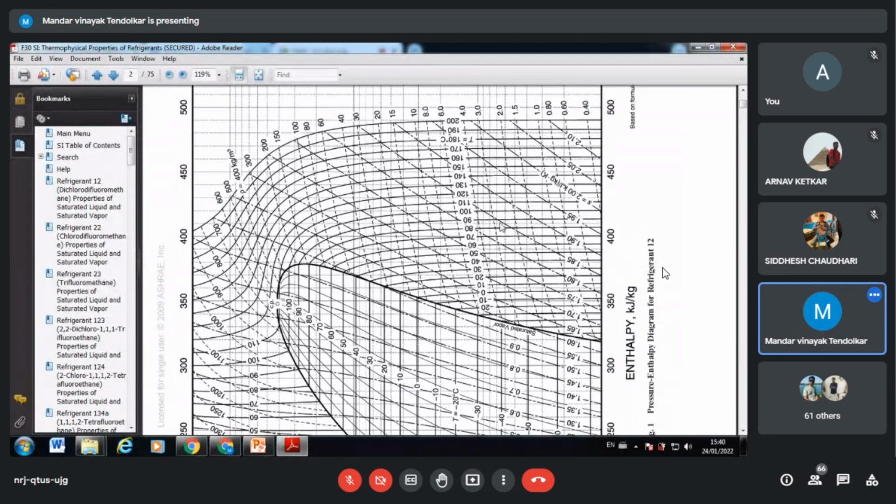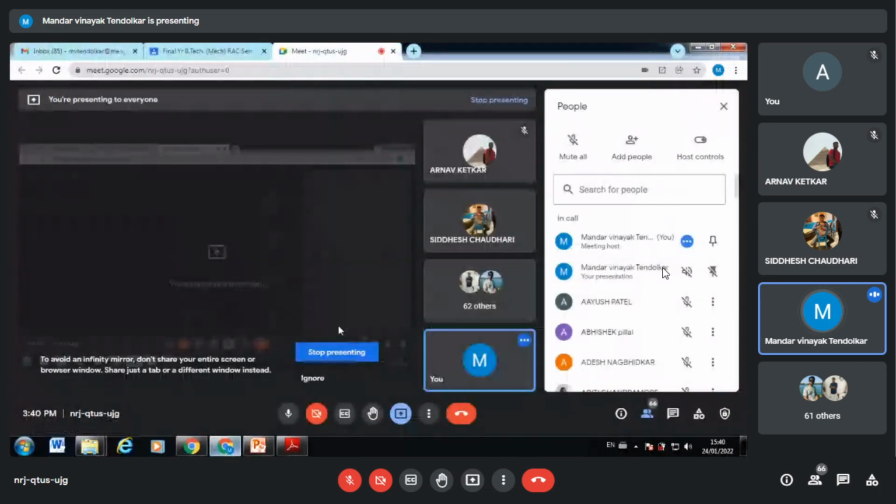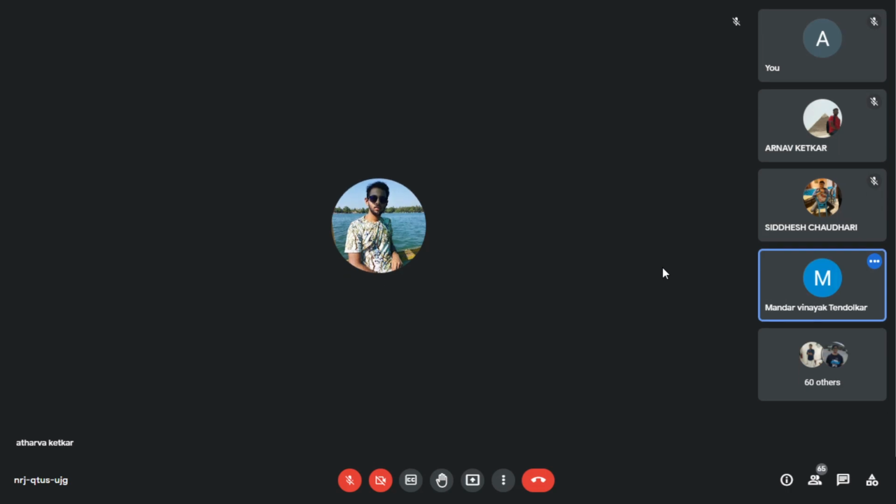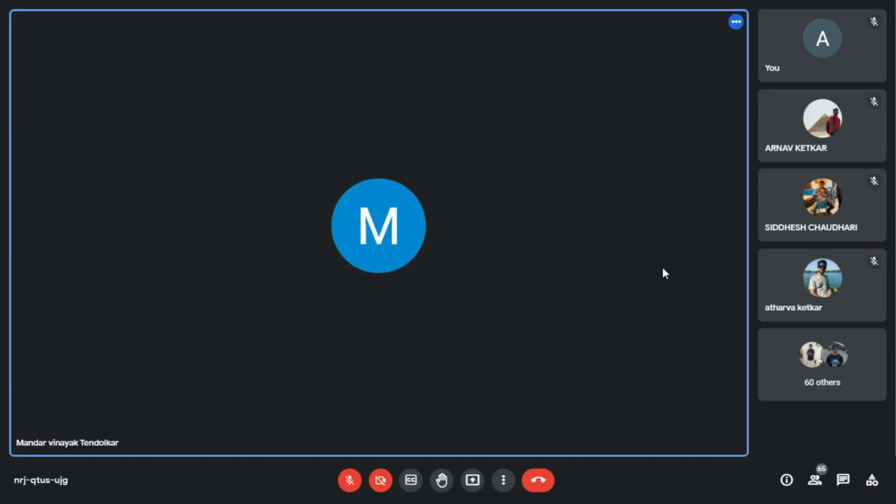They are different. So it basically tends to get flattened as you go on towards the right hand side. Tilt this 90 degrees the other way, assume, and then see that this slope and this slope are slightly different. Not slightly, quite different. So as you go on towards the superheated part, that means this is saturated, this is superheated, further superheated, then this slope is larger than this slope, which is flattened. Do you agree?